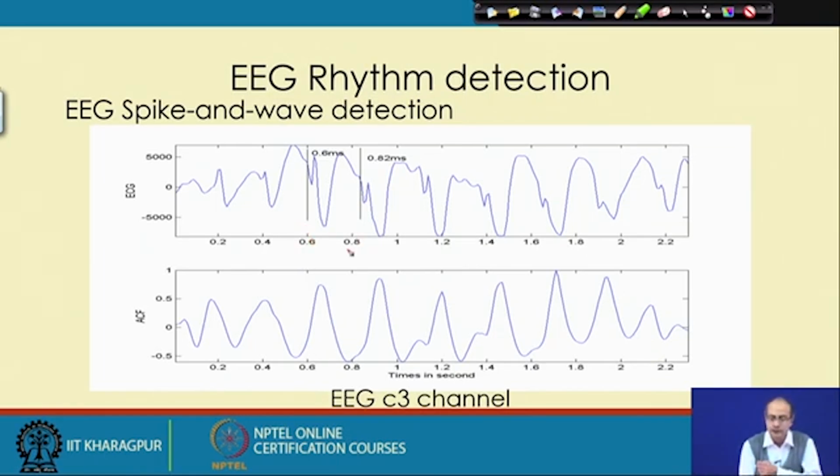While demarcating the boundary, we need to keep in mind that a spike and wave, as per the description, should contain one spike followed by a smooth, low frequency wave. So, we should capture both. If we take more than that, it is fine, but it should at least capture one wave completely, so that we can get a good output in the autocorrelation.